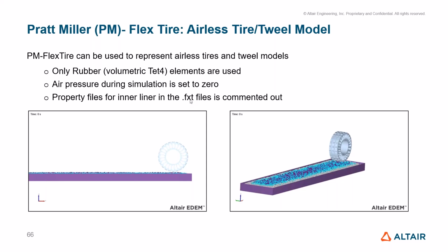However, for a representative simulation you can go with JKR with a very high cohesion model, or if it is a saturated condition, then there is a new contact model, the lubrication contact model, which includes hydrodynamic effects.